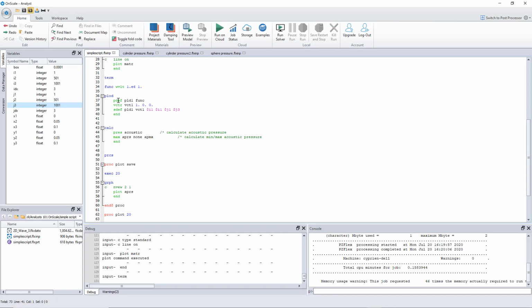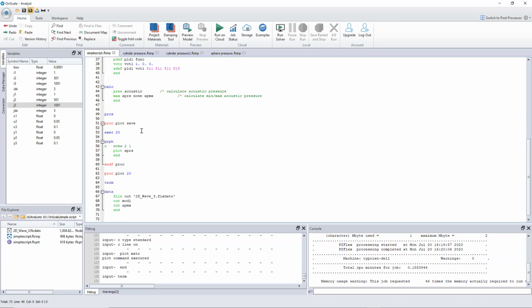So if I look at the plot here, I have the P definition, which takes a name, the driving function that I define here. It takes the vector for the orientation of the pressure. And the surface definition first takes the pressure definition, then it takes this vector here. So it uses the names that I defined before. And then it takes the definition of the surface, which is basically the left side of my plate.